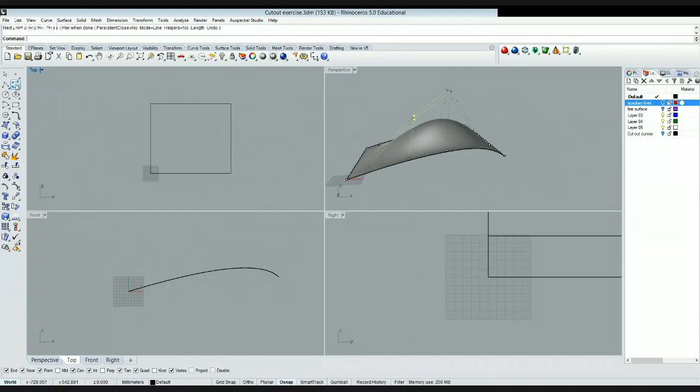And now I'm gonna do a control point curve with degree 3, and I'm gonna click on this intersection, make sure that your snap is activated, the intersection. So, and the midpoint, because I'm gonna snap now to the midpoint, and then here and here. So with these lines, I'm getting pretty close to my final shape, but I need to modify this curve a little bit. Something went wrong. Let me delete it and I draw it again.